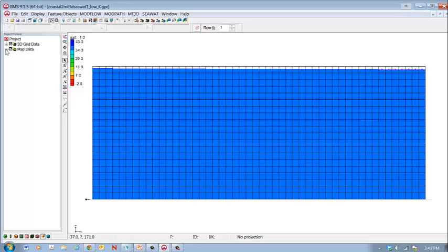So another effect that I wanted to show you is if we go and add in a low permeability layer. The model that we've set up is very idealized, and that's fine. It gives us an idealized look at how this works. But we might want to consider the effect of a lens. Back here, well, this is symmetric, but this depositional environment has a back bay where a lot of fine-grained sediments are deposited, and so it would be fairly common to have some clay lenses in this kind of setting. So I went in and put in a low K layer.